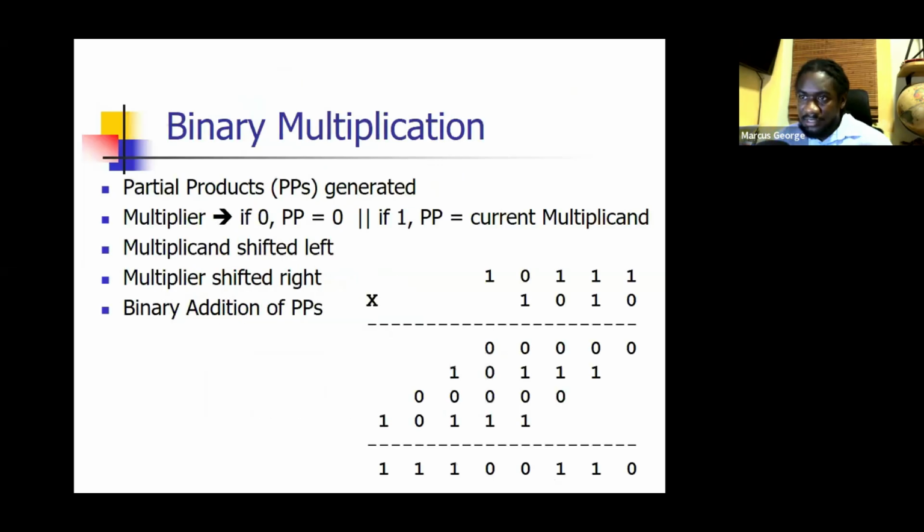For those of you that cannot recall what binary multiplication is, we have to generate partial products and then sum them up. So we have two parts: the multiplicand is the second one here, and the multiplier is the first. We are going to multiply. Look at the least significant bit of the multiplier, which is in this case 0. If it's 0, the partial product is 0.